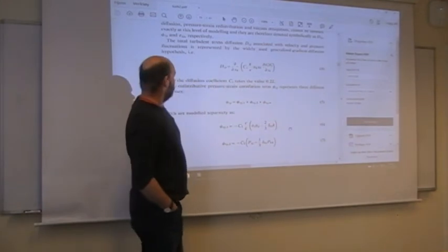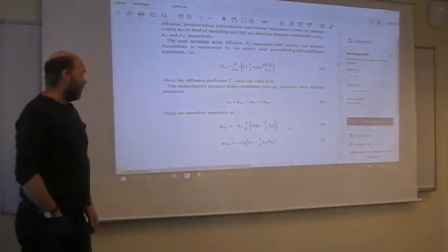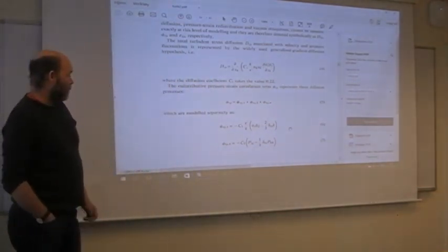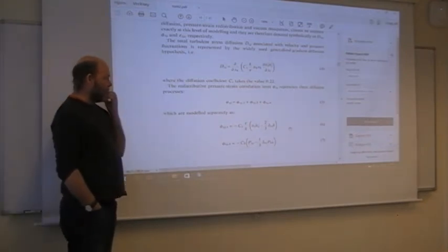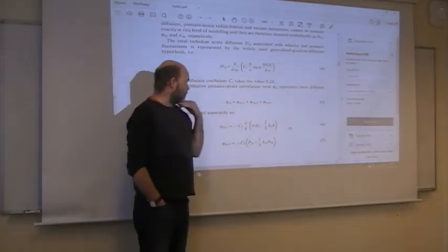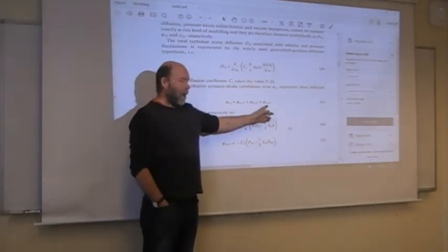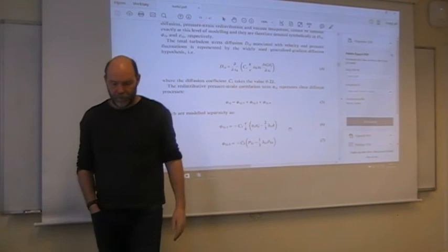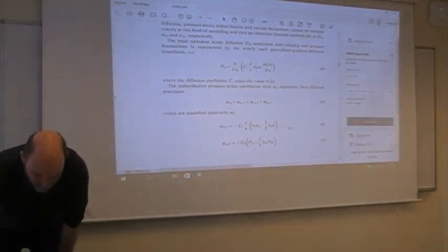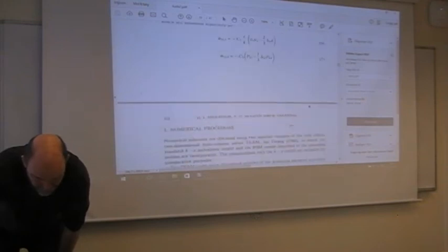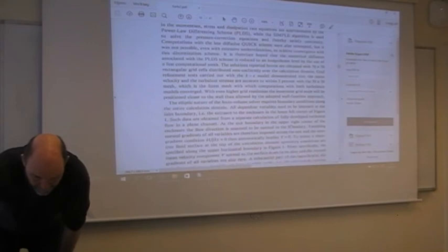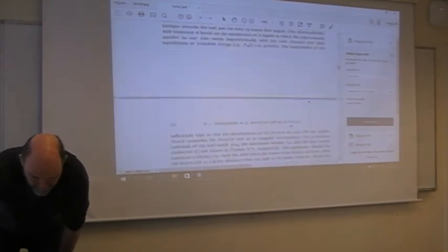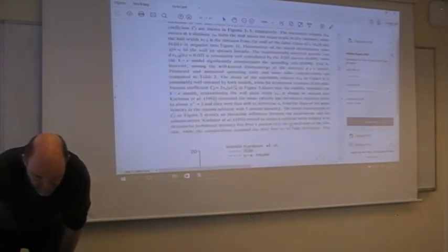Diffusion terms must be modeled, and then the pressure strain redistribution is here split up into several parts, and again a wall model for it. A separate special wall function, because close to the wall, that's actually where the activity happens. That's where all the action takes place.